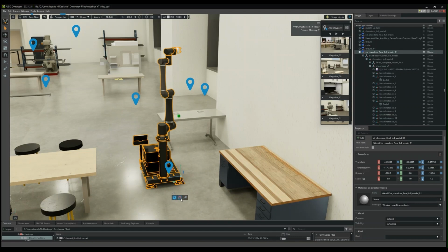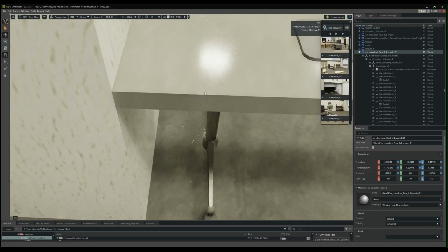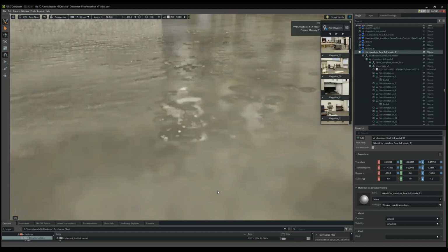Okay, now it's time to activate the snap tool. So I'm just going to click on the snap tool to activate it. But I'm going to make sure that my edge, surface, vertex options are selected, because we want the model to be snapping to the edge or the surface or the vertex that we want it to snap to, right? So now I'm going to click on the center point and move my model accordingly. So this tends to go haywire, right? The best way to do it is obviously have a good angle first.